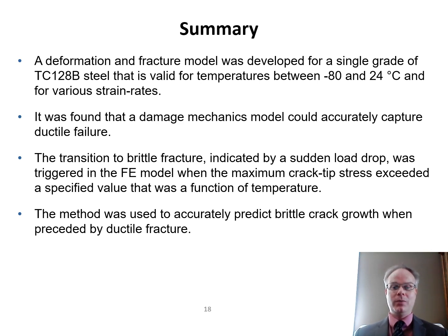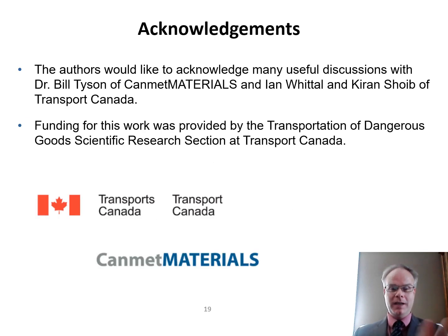What we showed is that we can take a model from literature in which a lot of work was done to calibrate that model, and then just tweak it a little bit, and we can still capture this wide range of material response. And to capture brittle fracture, we just did a little simplification with maximum stress in the model. When it exceeded a certain value, that triggered brittle cleavage fracture.